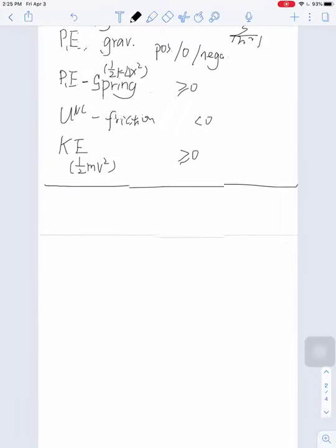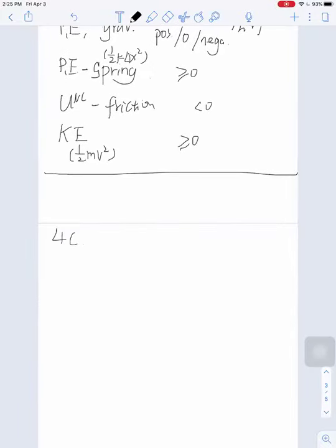So next, let's look at section 4C. In section 4C, we did a little bit of modification on F equals ma, and then we end up with the integral of the sum of forces dt equals m(v2 minus v1). And we're back into a vector equation again. So from A, B, C, only section B is a scalar equation. Both A and C are vector equations.